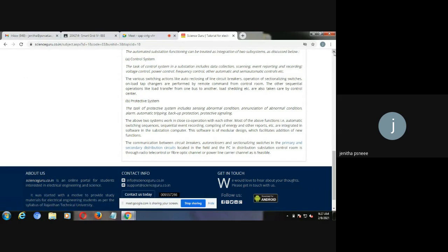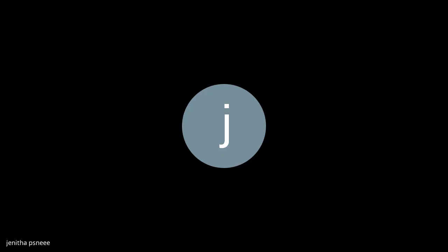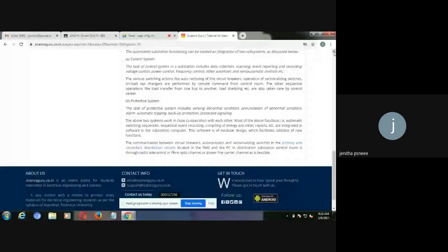We can indicate through an alarm or protective devices such as circuit breakers, relays, etc. This is integrated and interfaced with some software, so that if any abnormal condition is identified, it can operate automatically, because it can be programmed. It can reclose the switch or operate relays and circuit breakers, so that it can prevent further affecting the system.